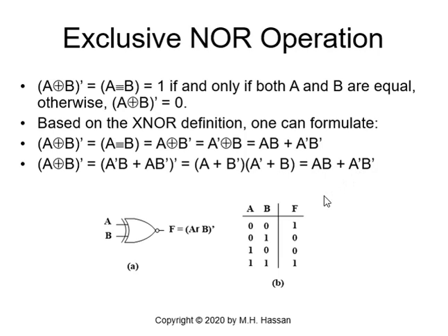As you remember, since we have 1 here, this will correspond to the minterm A prime B prime, and here the minterm is AB, so F will be 1 here or here, so F will be A prime B prime or AB, or we can say AB or A prime B prime, same thing, and you can see the value of function F, exclusive NOR.